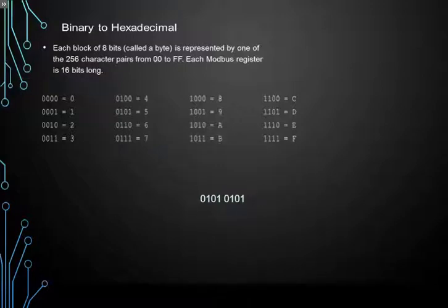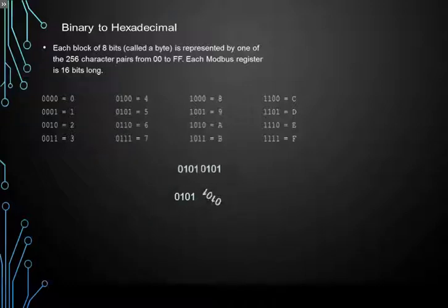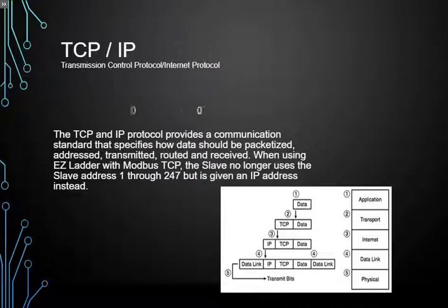The largest number that can be represented by a register of 16 bits is about 65,000. Of course, we need larger numbers than this sometimes, so 2 registers are used to store larger numbers. The order of the bytes and the bits can be a little bit confusing, but it usually just comes down to checking the settings during setup. You won't need to remember all of these details. The main thing is to have the settings the same on both devices.